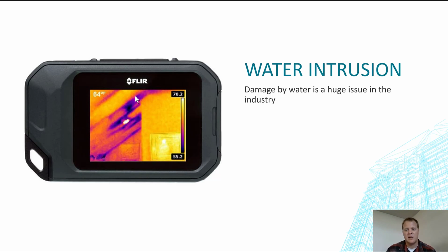It's just sitting there, not crimped, and it passed the test at working pressure. But over time, that pipe worked itself loose, and tons of water got into a unit. And then where does water go? It goes down, damages everything down below it. Keep going down, keep going down.